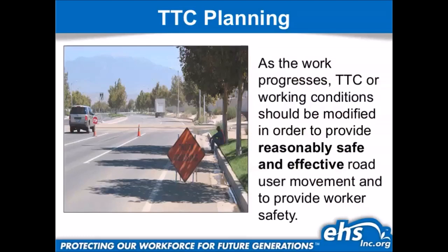As the work progresses, TTC, temporary traffic control, or working conditions should be modified in order to provide reasonably safe and effective road user movement and to provide worker safety. So basically what that means is as conditions change, and condition doesn't necessarily mean traffic only, this could be your work conditions as well. It's different to work daytime and nighttime, right? So if you're ever doing a project at night, one of those changes would be lighting requirements.